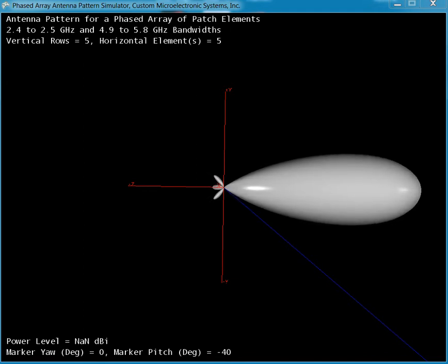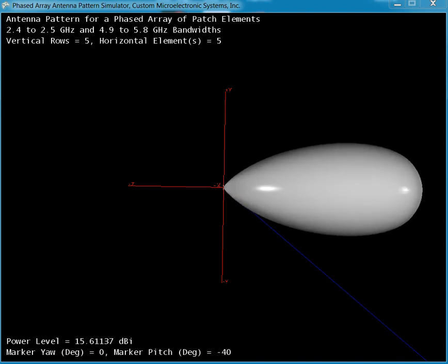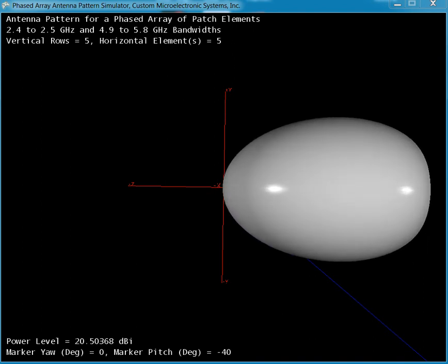And we're at 117 degrees inter-element spacing. As the elements become closer and closer, the beam width becomes larger, and of course your lobes become less in count and smaller in size. And of course, if you take this all the way down to inter-element spacing of 0 degrees, what you essentially have is 25 phased arrays stacked all into one. So you can think of it as a super patch element.